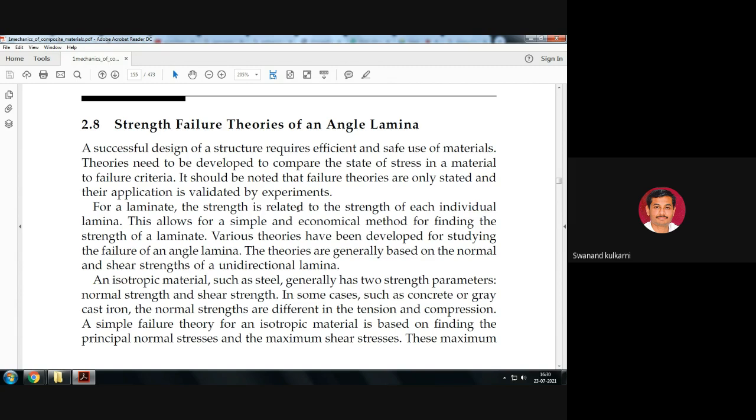In some cases, whenever we are considering the normal strength and shear strength, we know that shear strength is considered to be the maximum range to be half of that normal strength. If that particular material fails for 140 Newton per mm square, then definitely half of that, at 70 Newton per mm square, this material will get fail if shear stress is applied. Is it okay? So the failure of shear stresses will happen with the half value of the normal stresses.